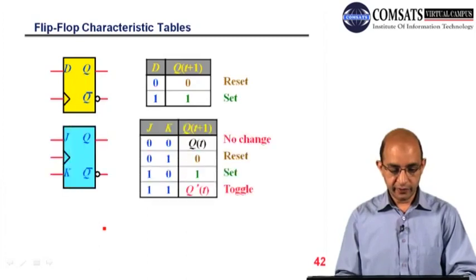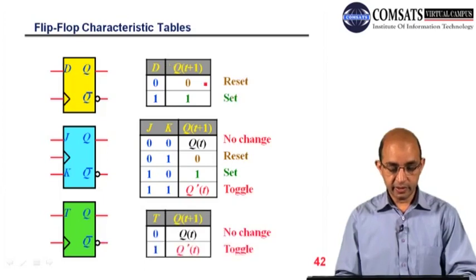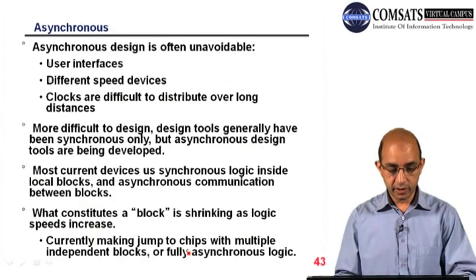And these are the flip-flops and their corresponding characteristic tables. We can also have the characteristic equations. So for D, Q follows D, except for these two, because here we have a toggle and here we have no change. So we are having the same toggle but with only one input. So T0 is no change, and T1 we have a toggle here.